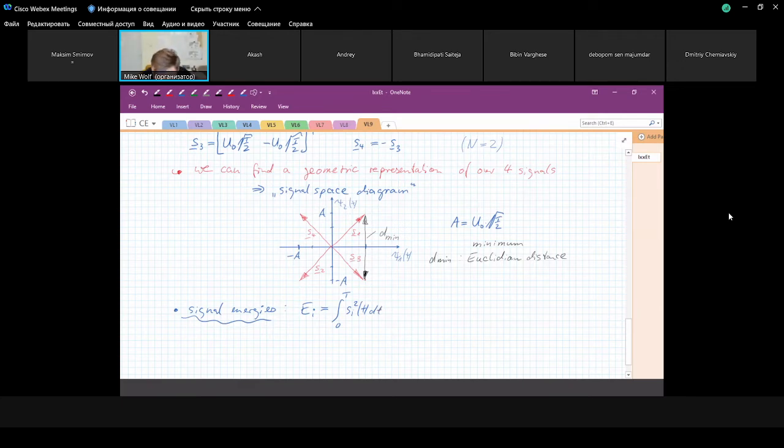But now we represent these signals as a linear combination of the basis functions. So this is s_i1 times c_1 of t, plus and so on, s_ij times c_j of t, plus, and the last one is s_in times c_n of t. We square this, dt. And now if we simplify this, we get this expression.